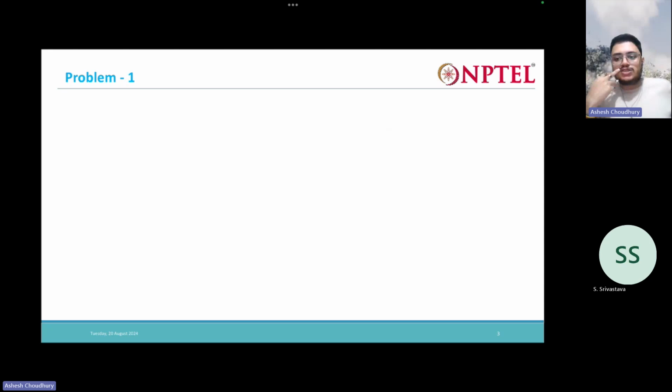First, we need to use the internal stability criteria to fix the spacing and the embedment length. So these were the main two internal stability criteria. The rupture will fix the spacing, and your overlap or the embedment length will be decided by the pull out capacity, right? By the pull out capacity. So let us start.